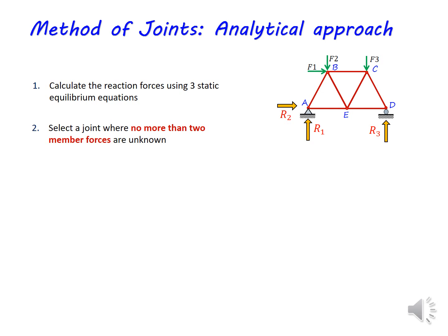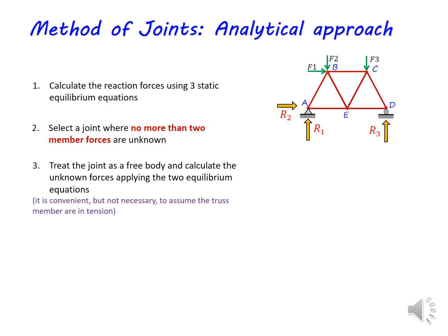Once you select the appropriate joint, the third step is to draw the free body diagram and calculate the unknown forces using the two equilibrium equations.